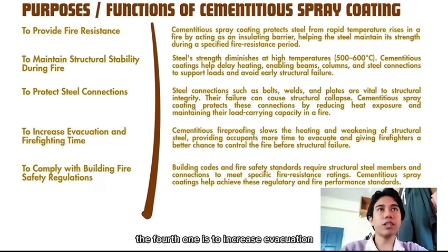The fourth one is to increase evacuation and firefighting time. By slowing the rate at which structural steel heats up and weakens, cementitious fireproofing provides occupants with more time to evacuate safely and gives firefighters additional time to control the fire before structural failure occurs.